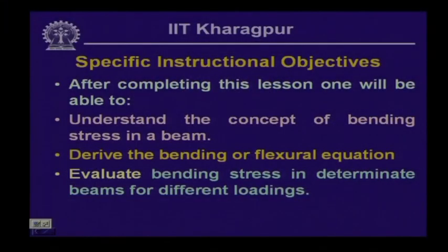One should be in a position to evaluate bending stress in determinate beams for different loadings. Here we are qualifying the beam by saying it is a determinate beam, as you have seen that for the beams we are dealing with, we can evaluate the values of the reactive forces based on the equations of equilibrium, and hence they are determinate. In this course, we are dealing mainly with determinate systems.